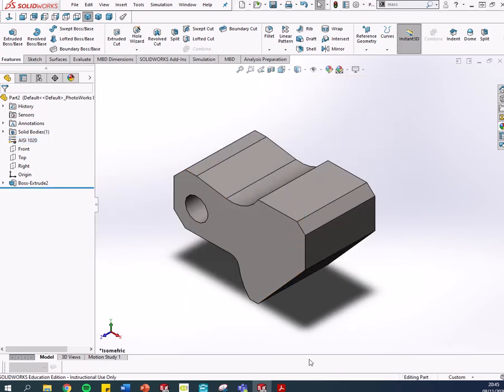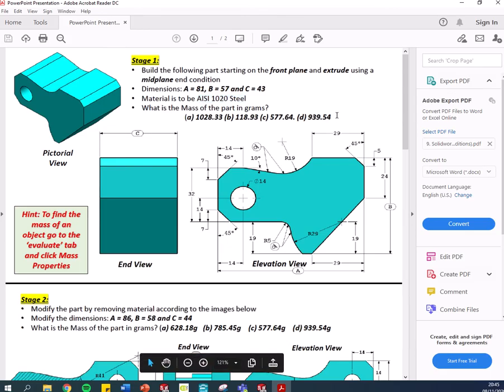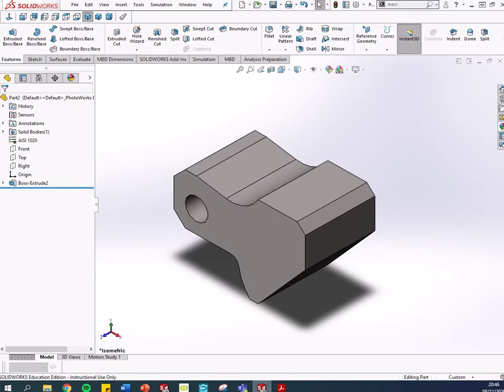That's grand. Now if I've got this right, I'm going to check the mass properties of it. So we've obviously drawn this to specific measurements, and we've made it 3D, so it has a specific volume, and Solidworks has the density of this AISI 1020 steel. So we have the volume and we have the density of it. So now what we can do is it'll calculate the weight in grams for it. Okay, so if I go to mass properties up here, type it into the search bar, mass P for properties.